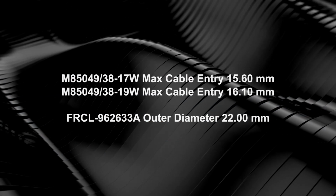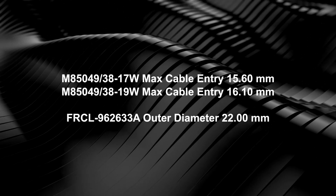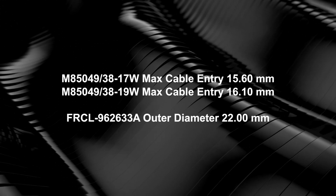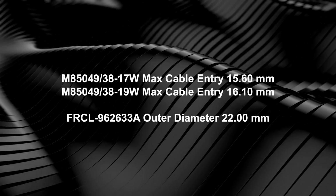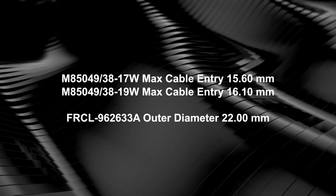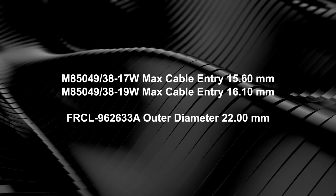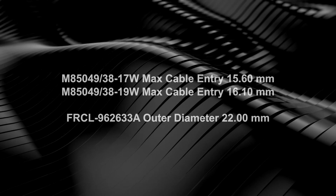Now, here's a summary of what we found. First, the parts list should have included 2 backshell part numbers. That's because the straight plug and the jam nut receptacle have different shell sizes. Second, the maximum cable entry for both strain relief clamps is too small. They cannot accommodate the cable's outer diameter, which is 22 mm. These two issues need to be resolved to ensure proper fit and function.